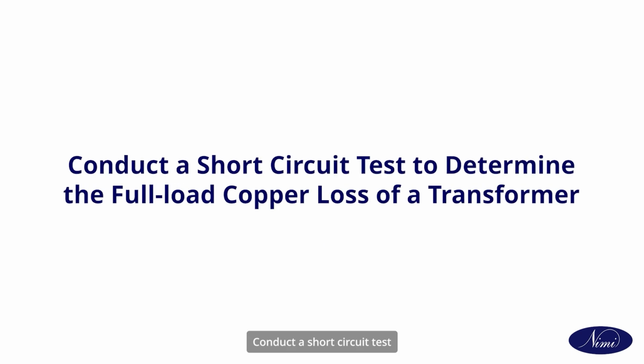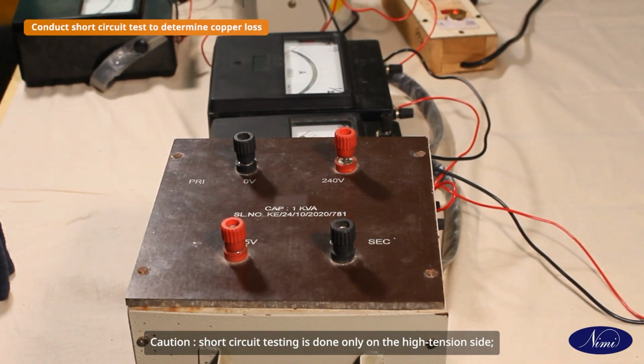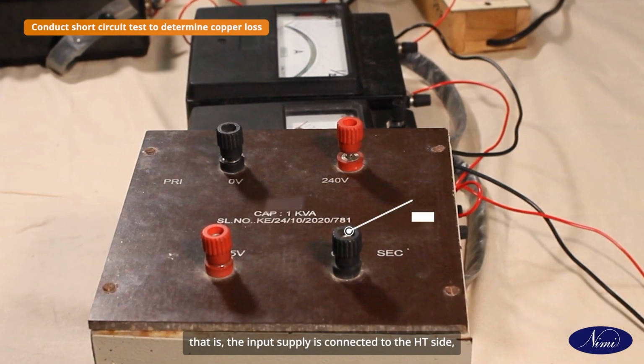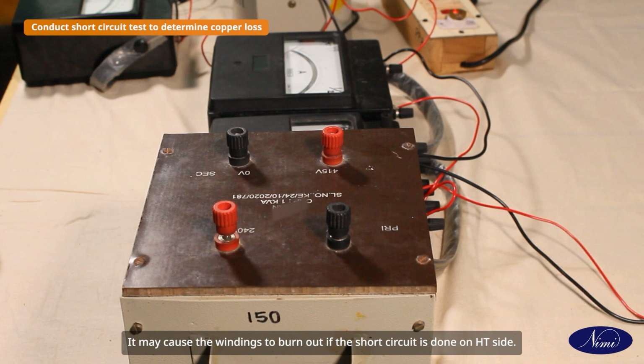Conduct a short circuit test to determine the full load copper loss of a transformer. Caution: short circuit testing is done only on the low tension side, that is, the input supply is connected to the HT side, and short circuit testing is done only on the LT side. It may cause the windings to burn out if the short circuit is done on the HT side.